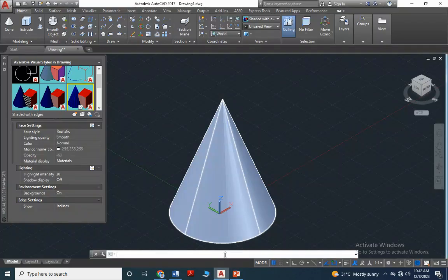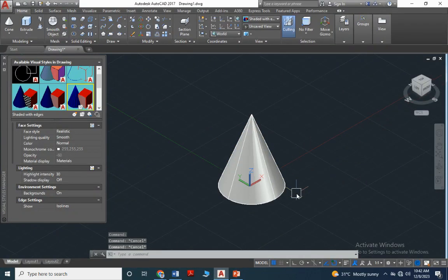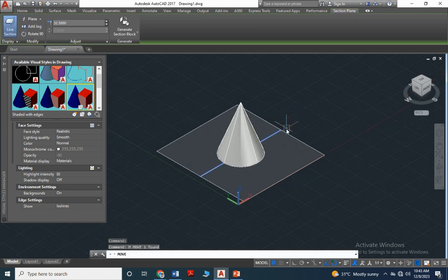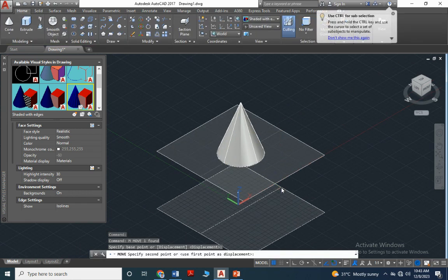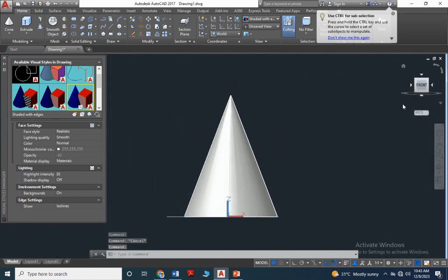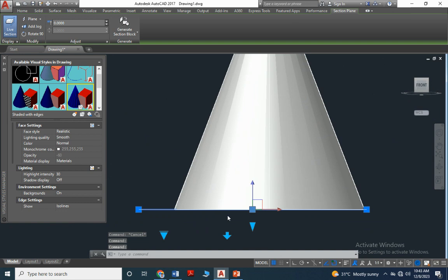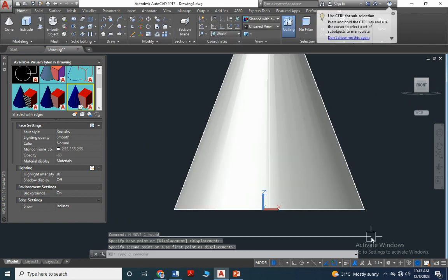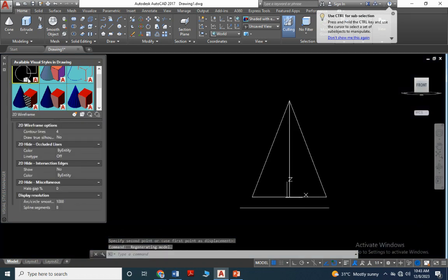Now I would like to draw the section plane, so just I type section plane, it is orthographic and placed at bottom, right? And first you move the section plane up to the bottom. See, now it looks like, yeah, exactly at the bottom or not, we don't know, right? So better you come to the section plane.